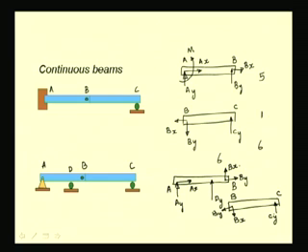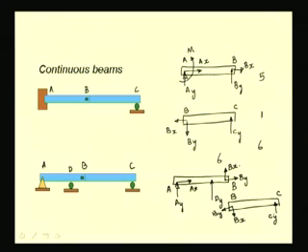So, let us count the unknowns that we need to determine and see whether we have sufficient equations. From this free body diagram we have to determine 2 plus 1 plus 2, a total of 5 reactions, and from this free body diagram only Cy is the additional unknown, since Bx and By have already been taken care of.